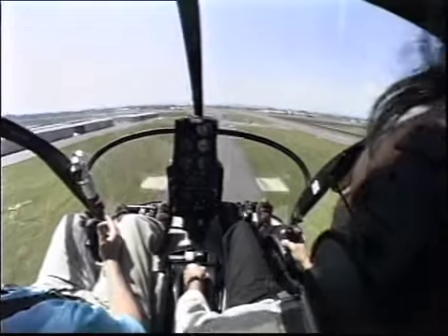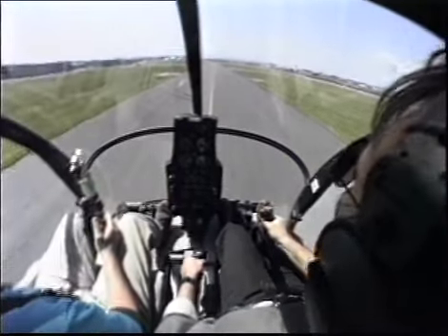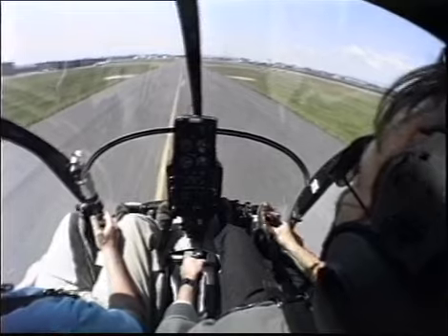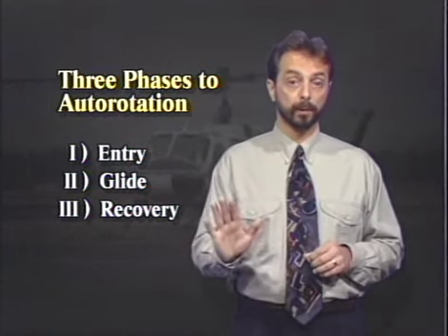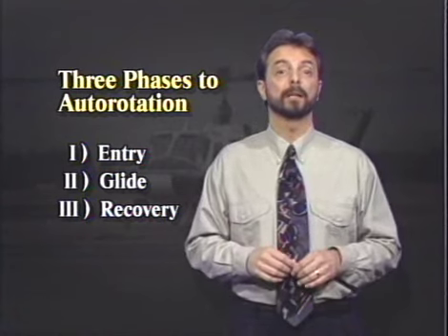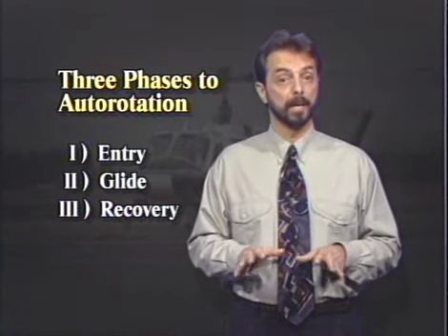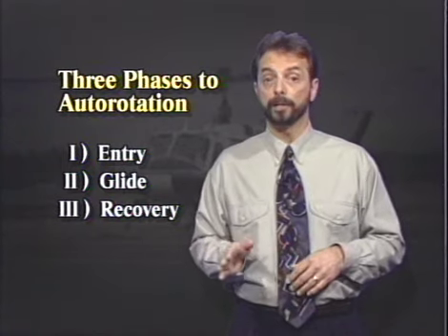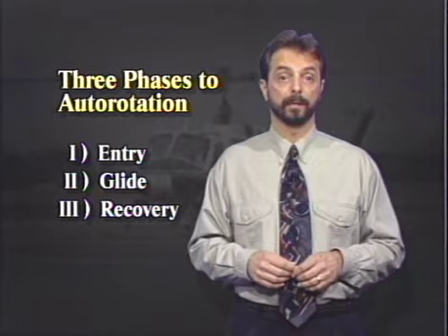As the rotor tilts backwards, the increased volume of air flowing through the rotor system increases the angle of attack and therefore increases lift. This momentarily slows both the forward speed and the rate of descent of the helicopter. It also will increase rotor RPM initially. However, as the airspeed and rate of descent approach zero, the RPM will again decrease.